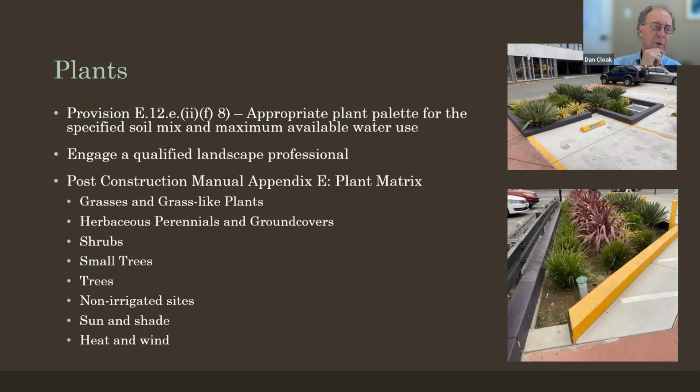And so the common practice among landscape professionals is, yeah, we'll just put some spray irrigation out there, and it'll hit this whole area, and the soil will stay wet enough that stuff will grow fine. And that overall philosophy and way of doing irrigation is not going to work in a rapidly draining soil.